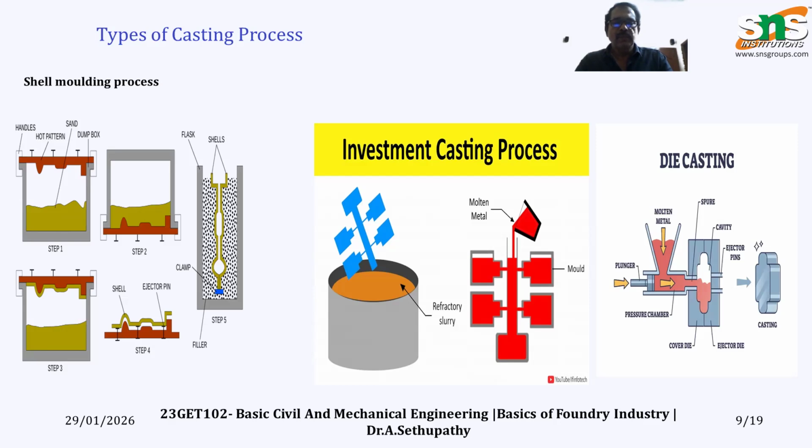The two parts are assembled and fixed inside a sand-filled vessel, like a drum or any other strong container filled with sand. So we fix the assembled shell mold and fill the sand around it inside the drum or box.